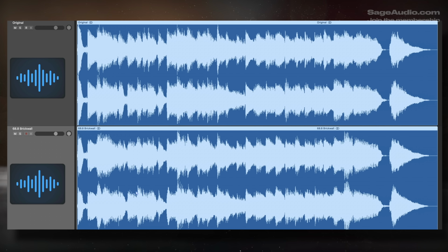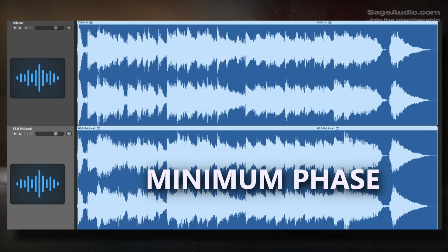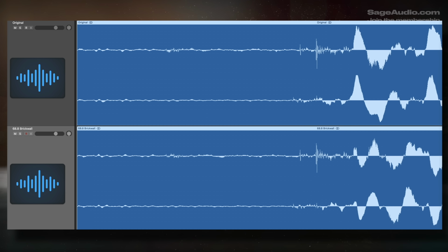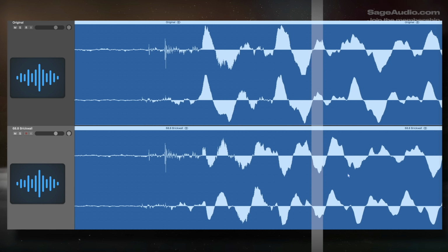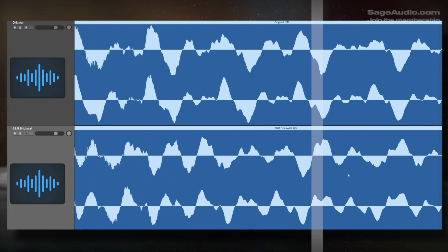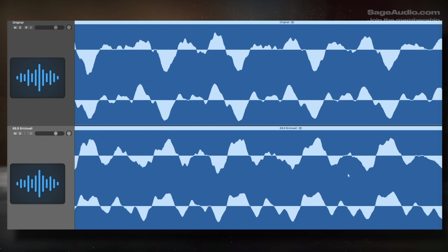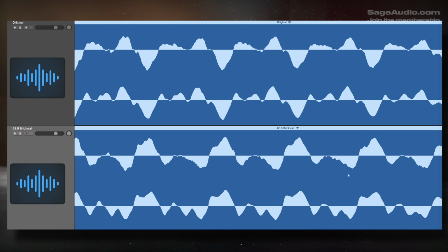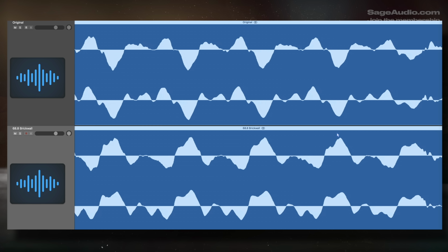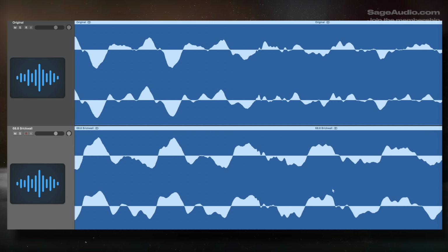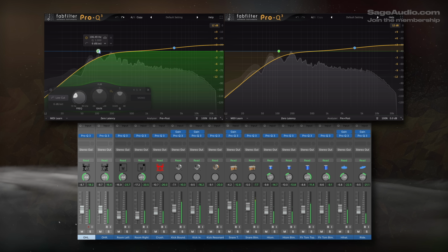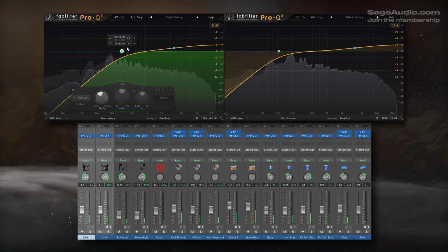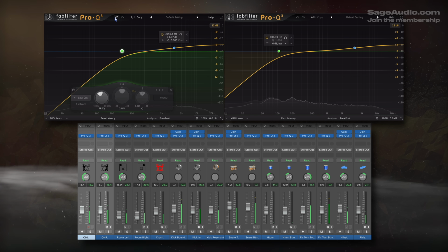Now, you probably noticed the minimum phase filter wasn't accurate in the slightest. When we take a look at the waveforms, note that very little phase rotation is occurring at lower amplitudes, but once the amplitude increases, aggressive changes occur, just like what we observed with the sine wave. This continues throughout the song. The polarity is completely inverted in spots, the waveforms are shaped and seemingly have different amplitudes and behaviors. All in all, this simple filter completely alters the signal. Now imagine the implications of this when you're processing multiple instruments with various filters, different dynamics, etc.